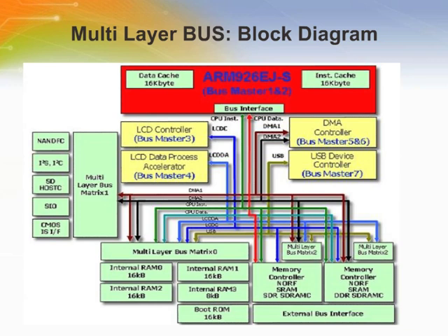Toshiba has incorporated 56 KB of built-in embedded RAM for program, data, and display memory, boot ROM, and a memory controller that supports SDR and DDR SDRAM. Up to 2.5 GB of linear access space can be addressed. An SD host controller supports high-speed mode SD cards with capacities up to 32 GB. The new microprocessor is supplied in a 361-pin FBGA package.